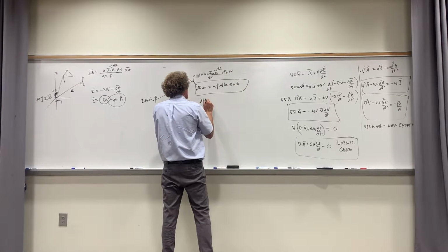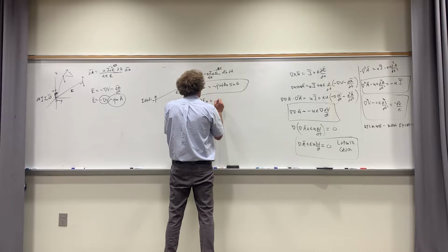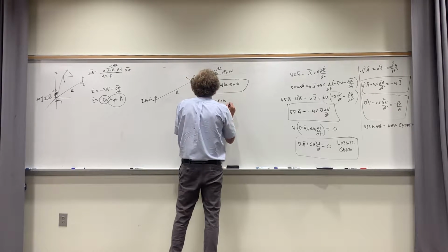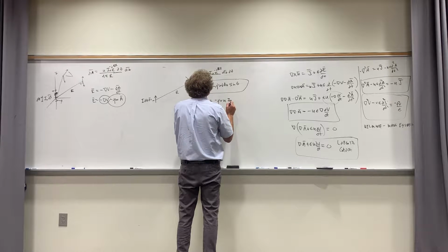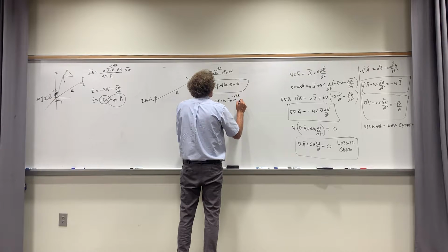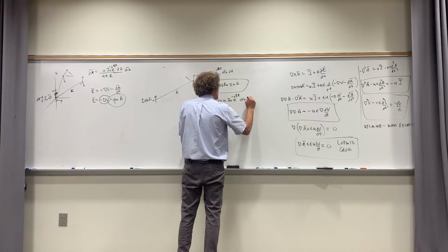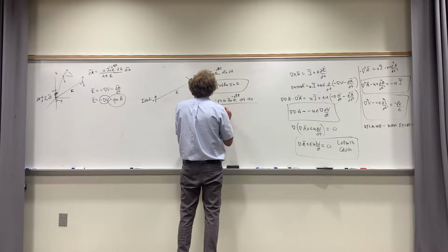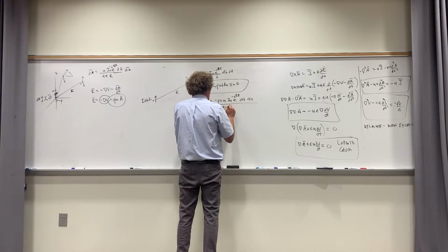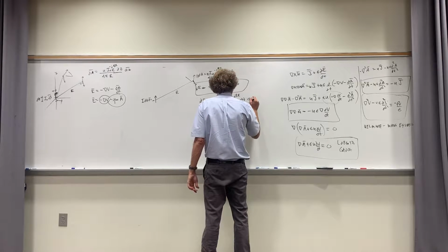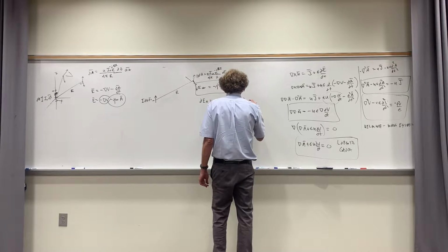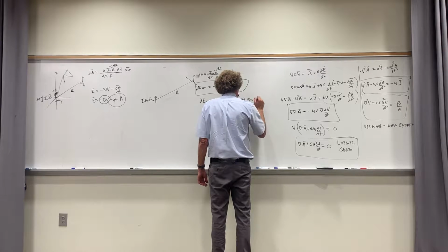I'm going to say that therefore dE theta in the theta direction is equal to minus j omega mu I naught e to the minus j beta r dz, write this down, over 4 pi r, and then this times the sine of theta.